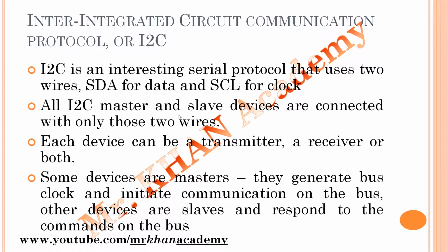All the I2C masters and slave devices are connected with only those two wires. Each device can transmit and receive or both. Some devices are masters; they generate the bus clock and initiate communication on the bus. Other devices are slaves and respond to those commands on that bus.